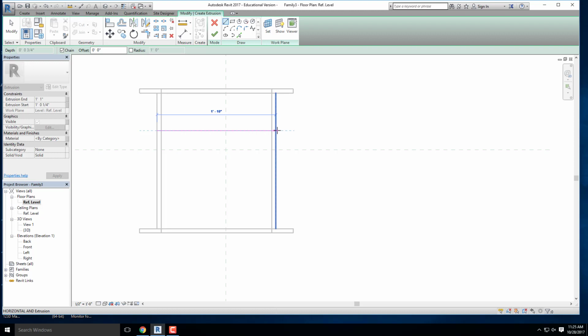So each of those spaces is going to be what? A 1/2 inch, right? Because the total width of all of our boards is 20 inches, and the width of our chair is 22 inches. So we have 2 extra inches. That means that the width between all of these boards is going to be a 1/2 inch. So we have 1/2 inch, 1/2 inch, 1/2 inch, 1/2 inch. That's 2 inches. All right.